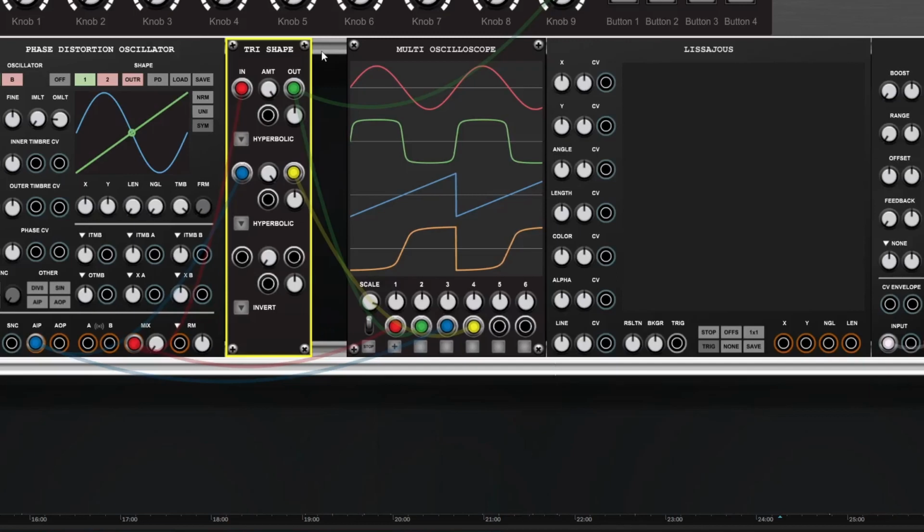The easiest way to analyze what a distortion module is doing is to run a ramp-up signal through it and visualize the output. When you remember the Waveshaper display, it's easy to see that the ramp-up is perfect for scanning over X values and get the corresponding Y values. Here we have the excellent multimode distortion module Trishaper by Weevil. This module packs an abundance of algorithms to shape your signal. For now, we are particularly interested in its saturation function. I have set the algorithm to hyperbole, and we can see in the scope what the transfer function looks like. The same applies to the cube algorithm, and so on.